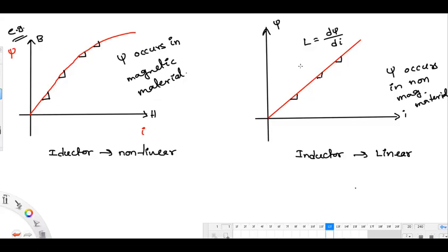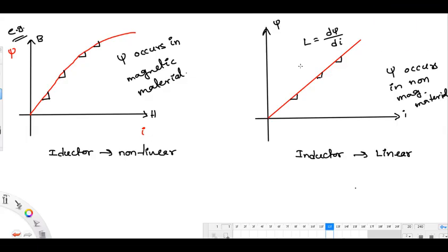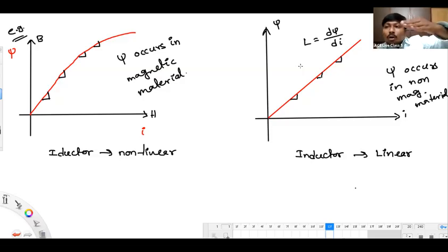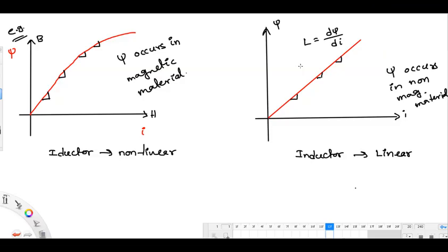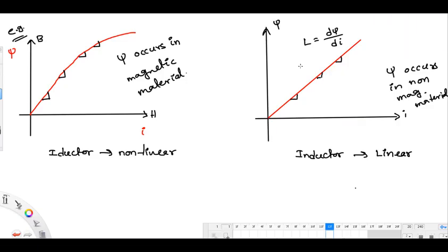It will fall in the intermediary category, between solid and AAC. Skin effect in the ACSR will be a little more compared to AAC, but less compared to solid. Transportation of ACSR is easy compared to solid, a little difficult compared to AAC. So it will fall in that category. Okay. Thank you, sir.